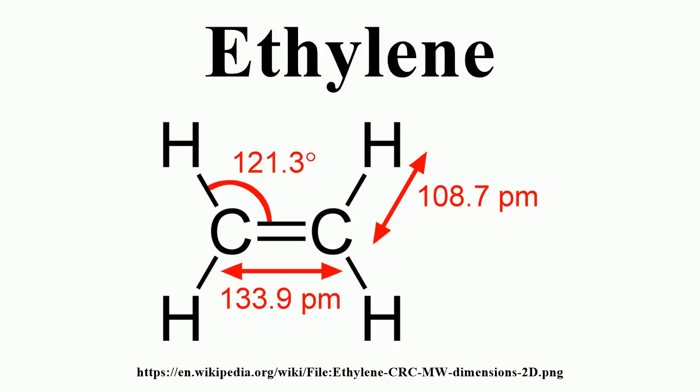An ethylene plant, once running, does not need to import steam to drive its steam turbines. A typical world-scale ethylene plant uses a 45,000 horsepower cracked gas compressor, a 30,000 horsepower propylene compressor, and a 15,000 horsepower ethylene compressor.